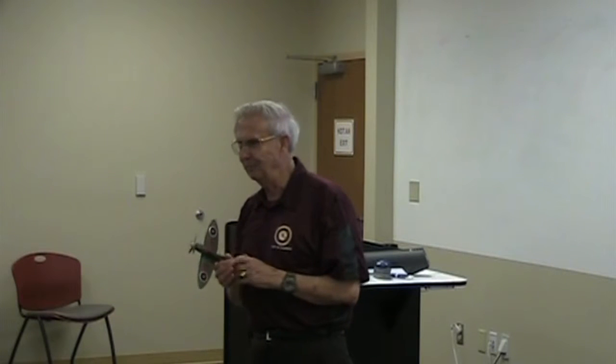I used to teach a lot of wind tunnel guys when I was in Tennessee, because we had the Air Force Arnold Center wind tunnel complex right next door. And they had a hard time understanding a lot of things. For instance, they had a hard time understanding the phugoid. Because with the phugoid, you get big changes of pitch, right? But the angle of attack doesn't change. And in a wind tunnel, if you've got so much pitch, it and the angle of attack are about the same.